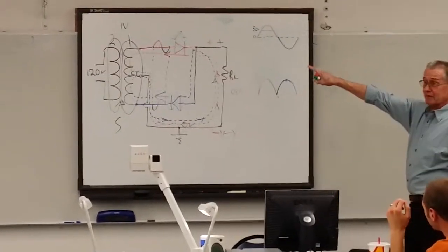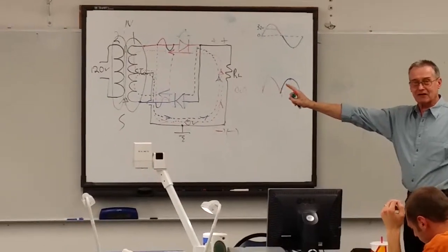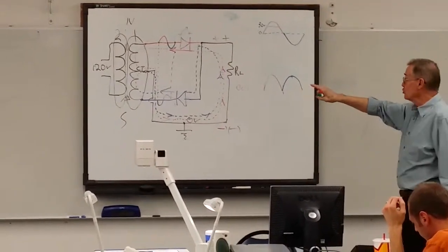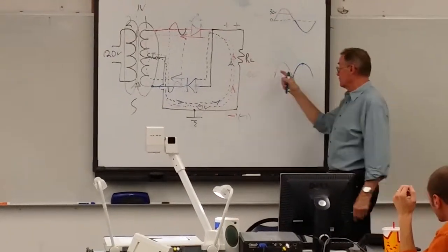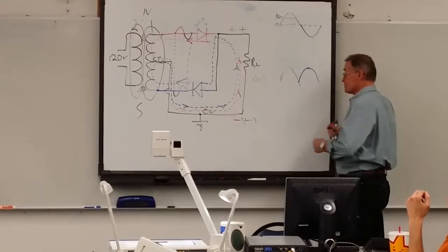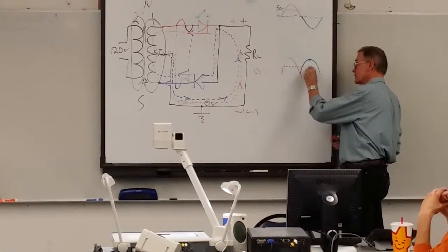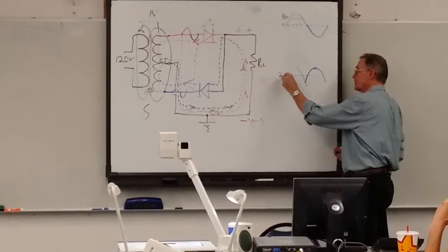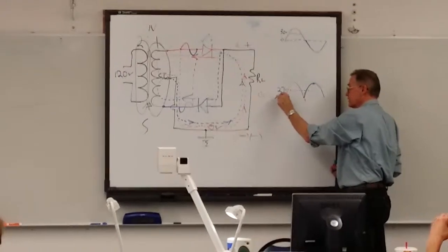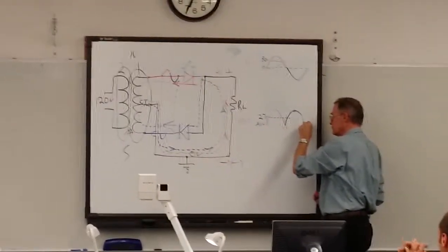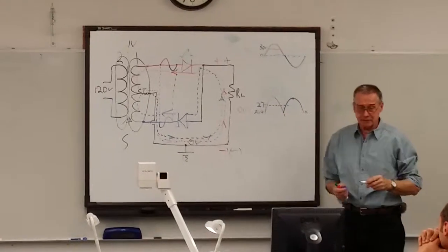All right, question, what's the voltmeter gonna read? We have a 2 to 1, just like the last time. The only thing is, we're only using 1/2 the transformer on each cycle, right? So the true RMS voltage is not 60 anymore, it's 30. So what's the voltmeter gonna read? Notice it's not 0 half the time now, Jeff. So it'll read 30? Yes, it will. Actually, it'll read 27 because that's the average of it. That's the DC voltage now. This is DC, right? Yeah. So it's gonna be average, which is 90% of 30, so 3 times 9 is 27.